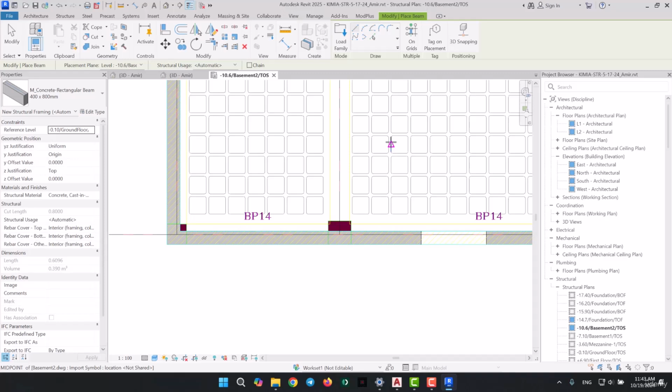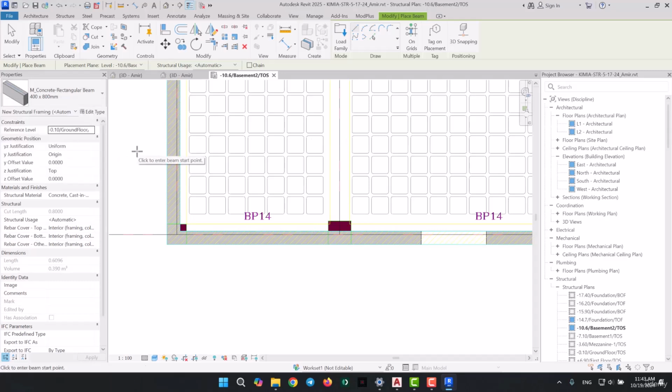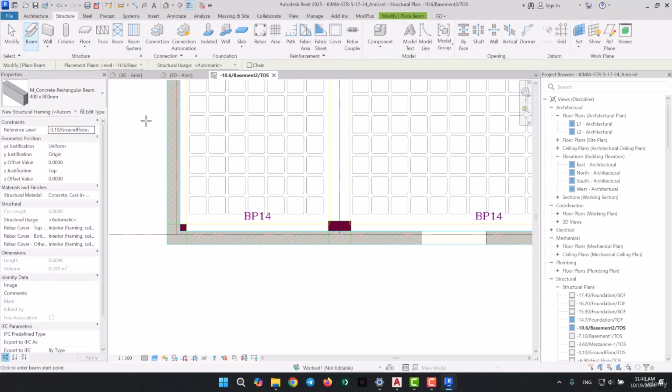So in case you have some older versions of Revit installed on your PC, you could use one of their default families and use them in your current projects. The older versions still have them. They have metallic beams, as well as the concrete ones. Now, in this 2025 version, if you go over to the Structure tab and select Beam, you might find some beams already loaded into your template. Like you could find some metal or concrete beams. So in Revit's default templates, we've already got some default families.